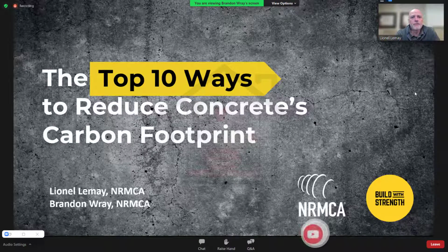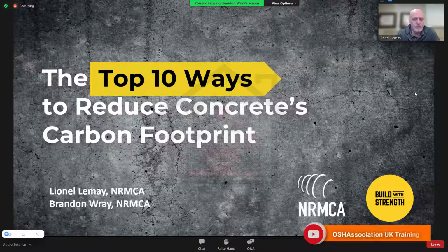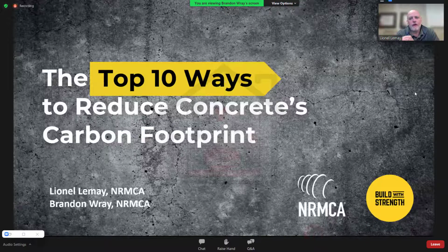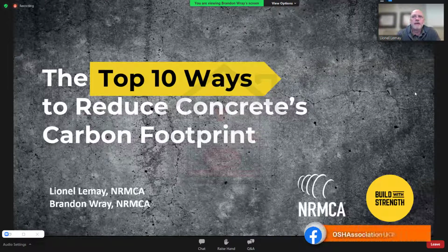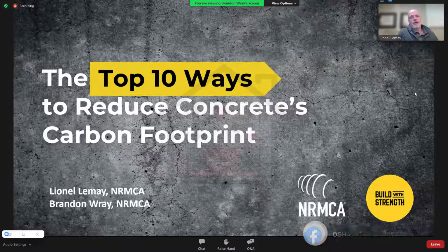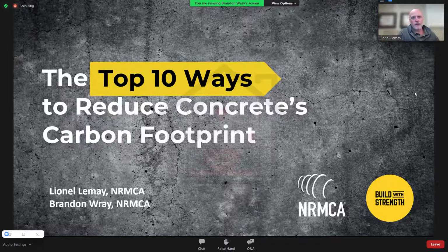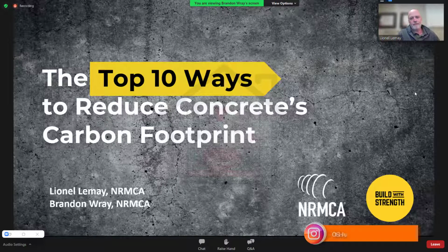And you're right, it is one of the concretes that is difficult to maintain a carbon footprint below a benchmark, the average 5,000 PSI concrete, for example. And I would say that this is the reason why we suggest doing a carbon budget for the project and not on each specific mix design, because for post-tension, you may have to go above the benchmark.